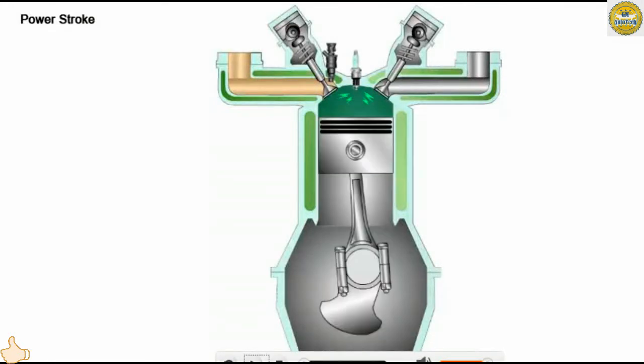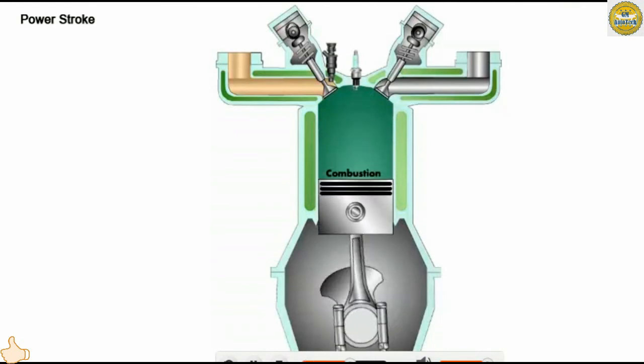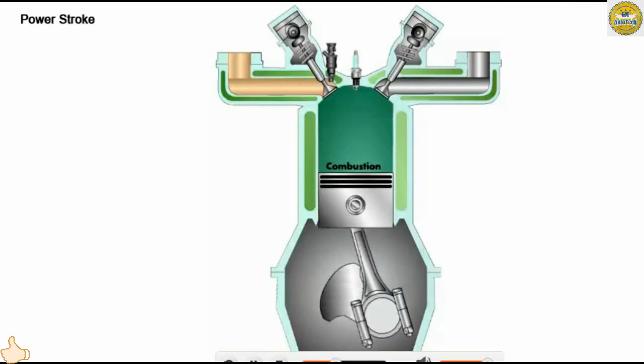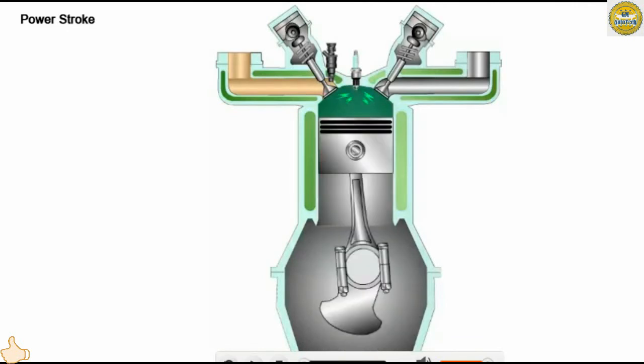Cylinder pressure increases rapidly due to the combustion and expansion of the burning mixture, forcing the piston downward. The downward motion is transmitted through the connecting rod to the crankshaft, where it is converted to rotary motion. The exhaust valve is opened as the piston nears the bottom of the power stroke, allowing exhaust gases under high pressure to begin leaving the cylinder.